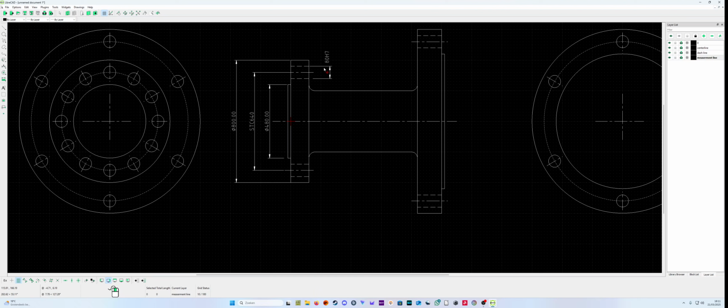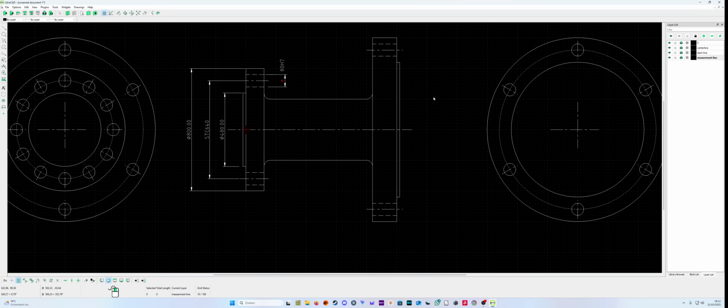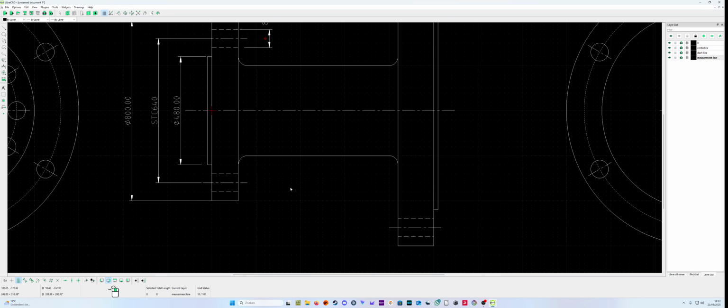It's also when you only put a measurement on one hole, every engineer knows that all the holes are the same. Yeah, this is 1, 2, 3, 4, 5, 6, 7, 8, 9, 10, 11, 12 holes. So everybody knows the 12 holes, if it's not specified further, are all 80 H7. Yeah, so that's a written rule a bit.